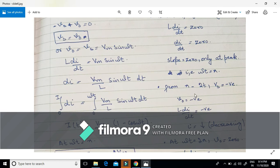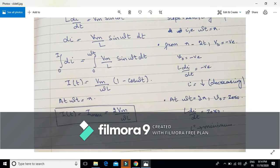Similarly, from pi to 2 pi, as the source voltage becomes negative, the voltage across the inductor, that is equal to V output, is negative, or L di by dt is negative. This differential is negative only when the current is decreasing.